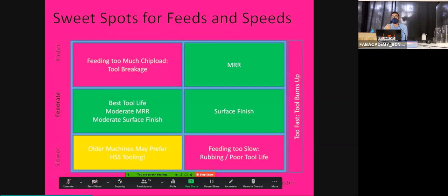If you are cutting too slow, there is not enough material, chips, to cool the end mill, and it will heat up and destroy the end mill, or not cut really well on your material, or make a fire, depends. There is a really easy rule to know if you are cutting well or not, and it's about noise. I always like to say that CNCs are like babies.